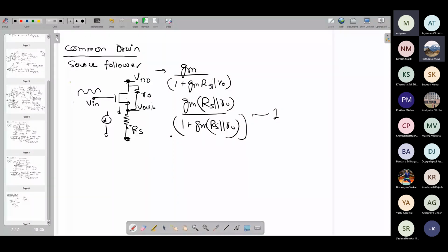Now, looking at the actual circuit, ultimately the way we bias is using the current source. We use a current source with some bias voltage coming from a current mirror, and the input signal is over here. Now we can figure out what the output signal swing is.